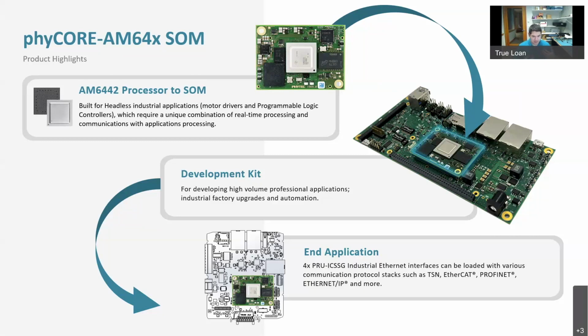Once you have a prototype built around the development kit, you could literally copy and paste circuits from the development kit that you know and trust work, and adapt them into a custom carrier board. You pick and choose your circuits so that you cost-optimize the size, shape, and function of your board for your custom application.